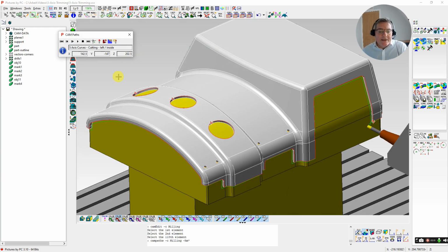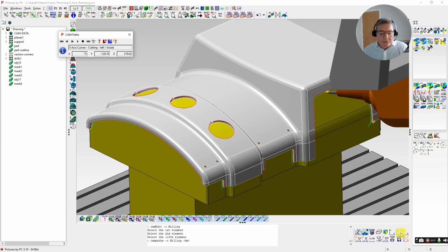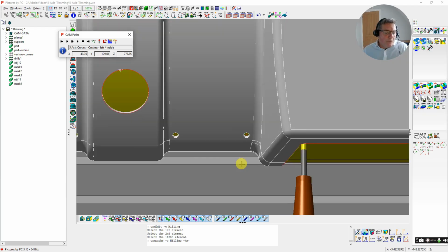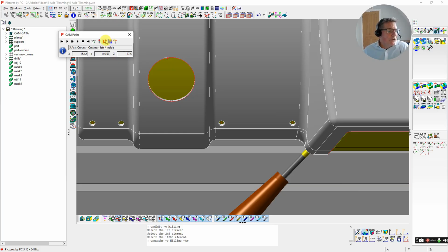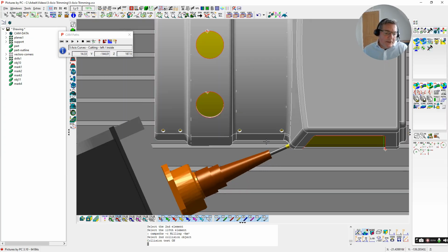You'll see here we're staying to the left of the contour. We're tilting the tool upwards as we stay perpendicular to the surfaces. Everything's looking good. If we look down from the top here, we'll see we've got surfaces with quite a strong curvature. If we remain perpendicular to these, we're going to tilt quite dramatically. So I'm just going to turn on the collision control between the machine head, the holder, and the part, and see if we have a collision when we tilt.